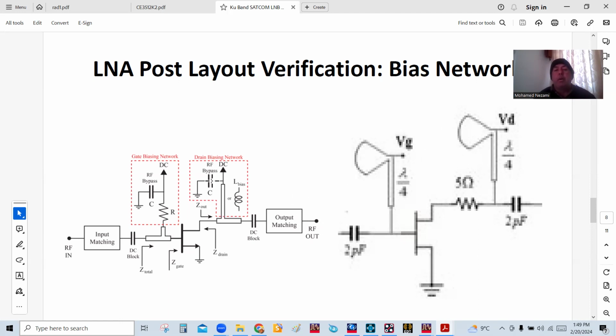And of course, we put a cap in here. We have to put a cap in here if it's microstrip, because as you know, this section in here, if you implement it in microstrip, is a quarter wave section. And for a quarter wave, as you know, it's an impedance inverter, and I'll show you in a minute with the equations. I'm assuming that you all are familiar with that. A quarter wave transformer inverts the impedance. If the load is 0, the input impedance of the quarter wave section will be open. And that's what we're going to try to do here.